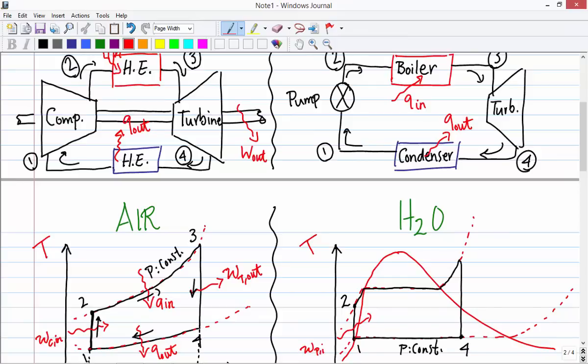And we are adding the pump work, which goes in. Then what do we have? We have liquid at high pressure, and it's ready to absorb energy, right? So we send this to the boiler and say, okay, now you're at a high pressure. That's awesome. All you need now is a high temperature. So let's warm it up. Let's add heat to it. Therefore, it's going to boil.